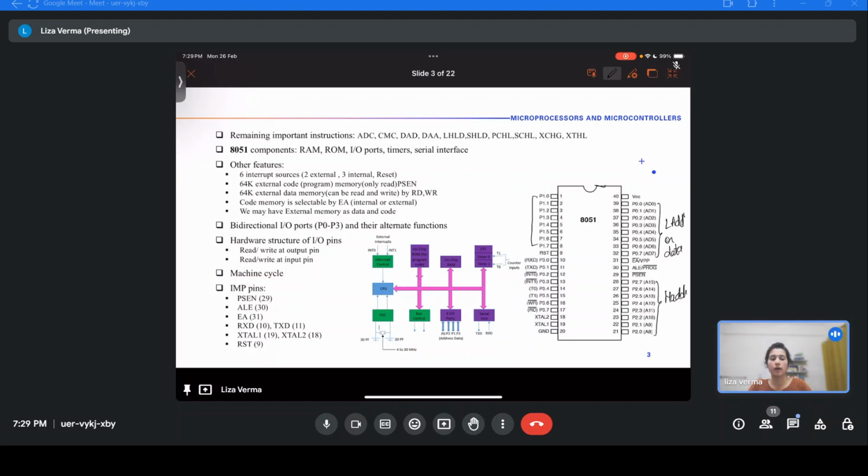There's a particular location that the stack pointer has to point to. 07, yes. So that whatever the starting instruction is, if it is to push some data onto the stack, the stack pointer has to be at some known location, right? So after reset, the stack pointer will point to 07H, and where will the stack pointer point to after the first push?